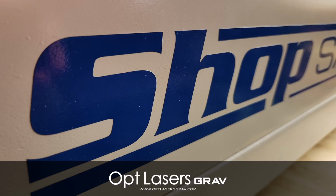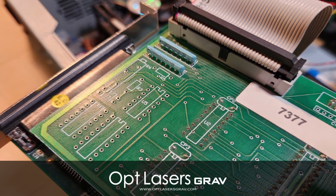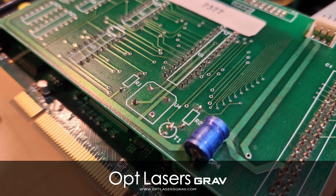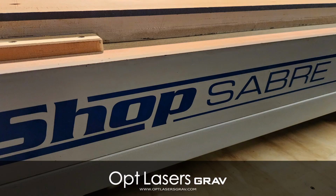WinCNC 3.0 uses a daughter board that features a 3-position jumper head in the middle of the board. The jumper is placed on pins 1 and 2 by default for normal operation. In order for WinCNC to be used for laser, rastering, or vectoring, this jumper will need to be moved onto pins 2 and 3 before installing back into the computer. Setting the jumper to the laser position will cause the 5th axis to output laser pulse rather than traditional step and directional signal. Once the boards are reinstalled, the setup for WinCNC is complete.